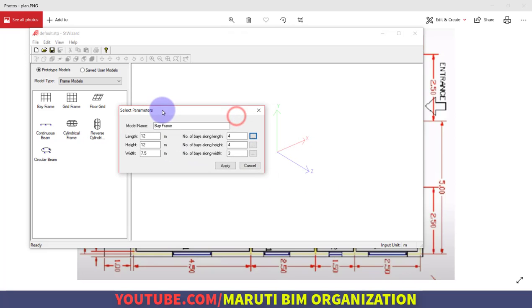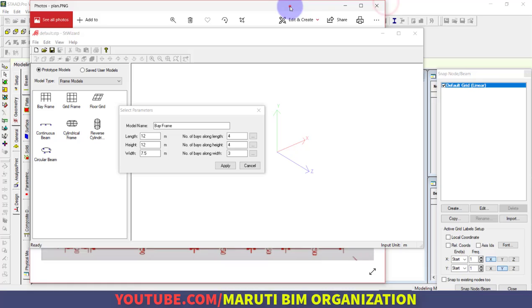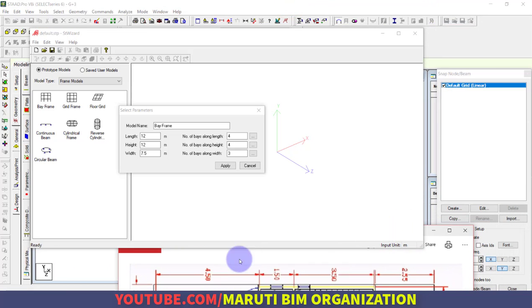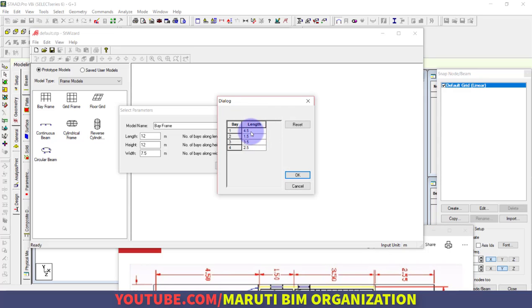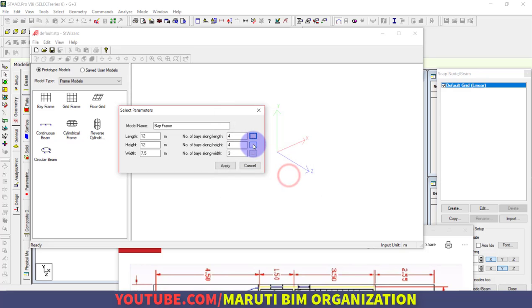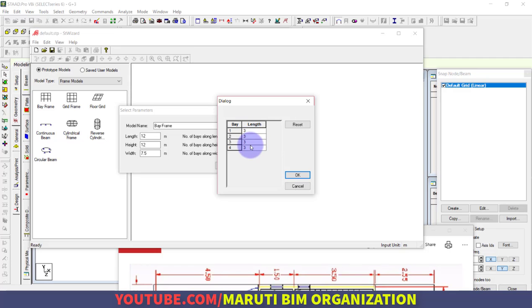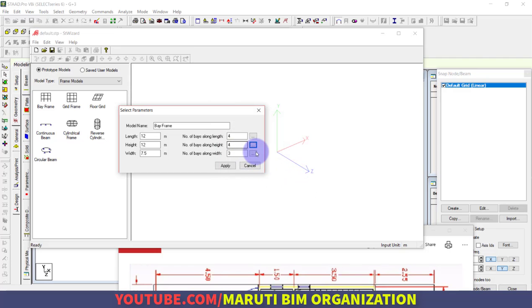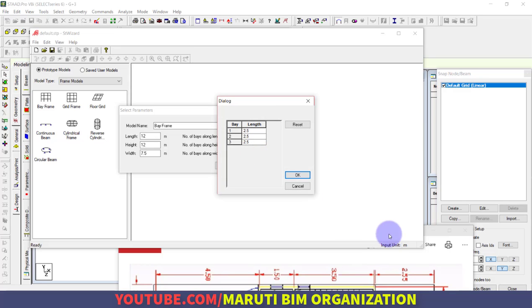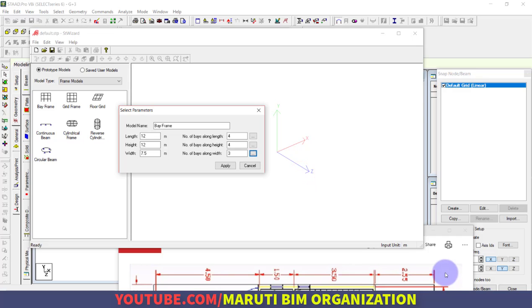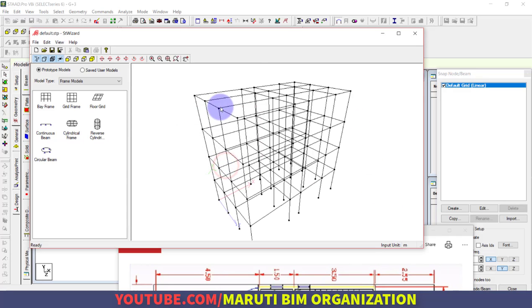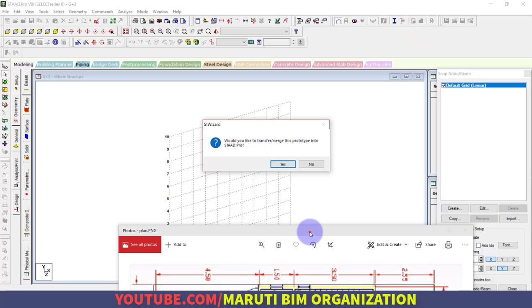And then, as you can see, if I scroll to this plan, first you can see 4.5, 1.5, 3.5, and 2.5. So that is how I have defined it here: 4.5, 1.5, 3.5, and 2.5. In the y direction, all is 3 meters, so 3 plus 3 plus 3 plus 3, and similarly vertical, this is 2.5, 2.5, 2.5. If you observe this plan, that one becomes 2.5 plus 2.5 plus 2.5 in that direction. Now I will simply close this and run the structural wizard.